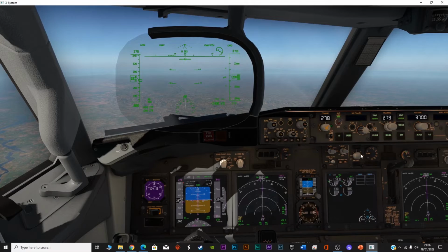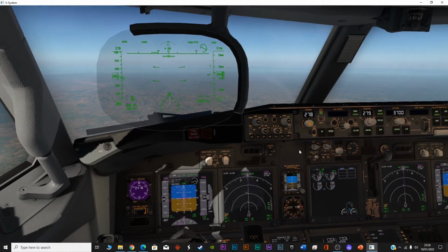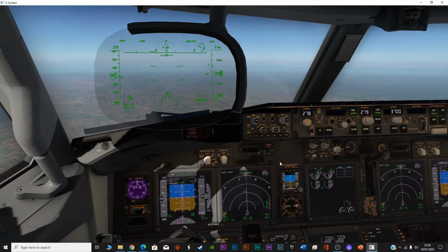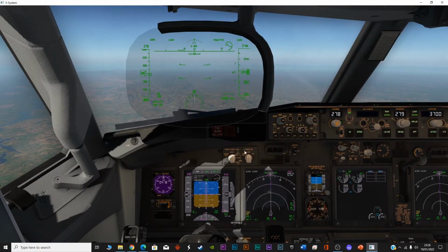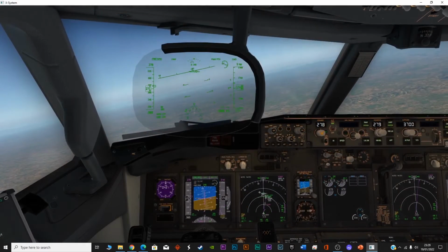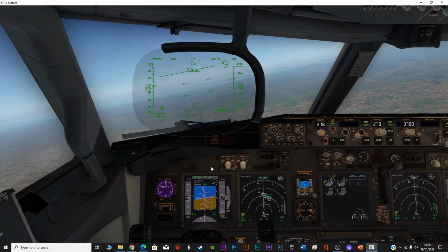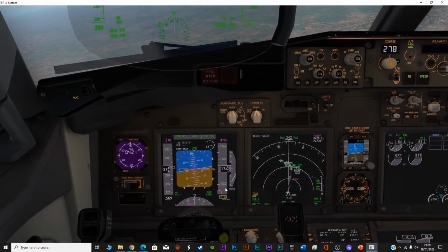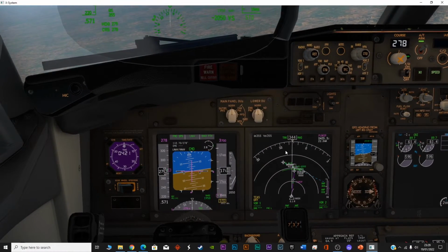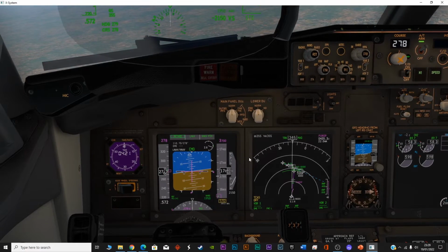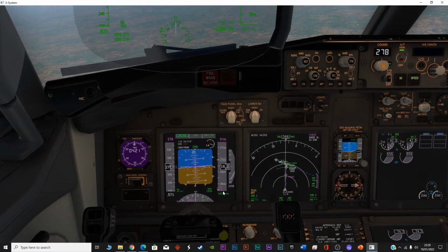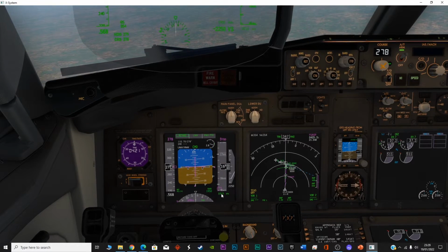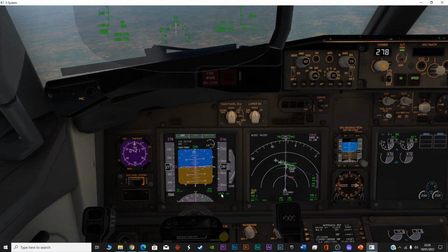So the brakes I've already set to max, and the heading is given. Altitude, glide slope set, and the ILS frequency is given. So these are the settings that you need, and that's it. Now you can see on the screens, over here in the primary flight display, the standard has changed. It's coming in a box with a yellowish mustard color. I don't know, I'm very bad with the colors. So if I press this option, now the atmospheric pressure is changed from standard to the given one. That's the 1013 that I selected. So everything is looking good so far.